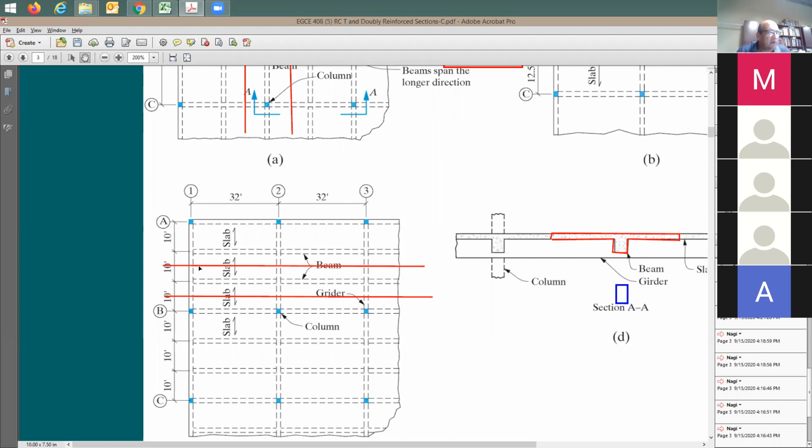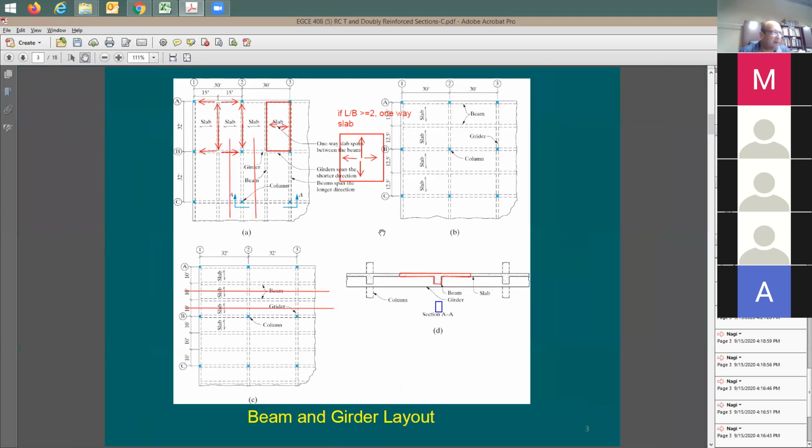The slab thickness also is going to be a factor. And the code says that you need to take a certain width based on the slab thickness, the tributary width, and a fraction of the span. We're going to be going through this later on. But for now, I'd like to confirm here that the maximum flange width is going to be equal to the natural boundaries, which means the spacing from one beam to another beam. We call this tributary width, if you like.